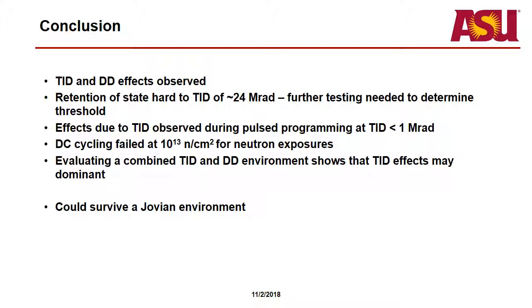With the TID, we have material evidence of the transition from alpha to beta, but displacement damage can also cause that transition, because if you disturb that germanium background that's putting pressure on those nanocrystals, for example if displacement damage breaks one of those germanium bonds or causes scattering, you release that pressure on that nanocrystal, and then it transitions from the alpha to the beta phase, which is less conductive.